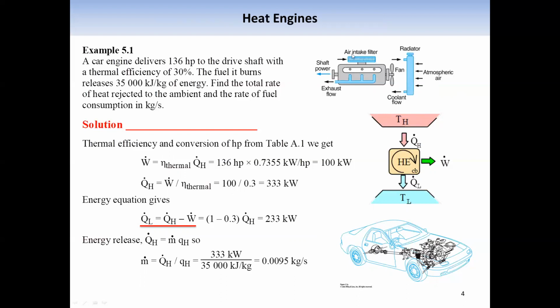The working fluid in this case will be air and the fuel as a whole. And if we know the fuel burns and releases 35,000 kilojoules per kilogram of energy, that's QH dot.